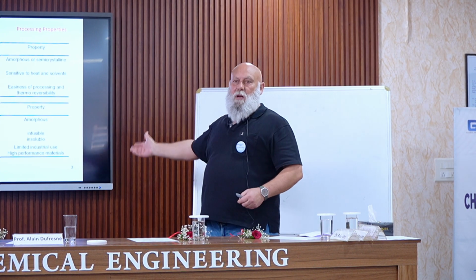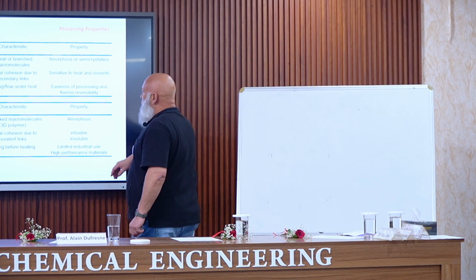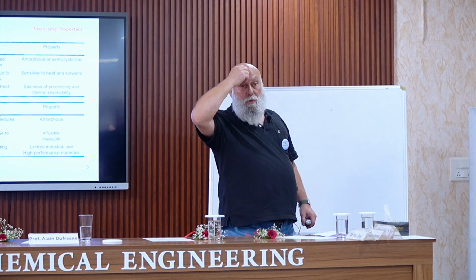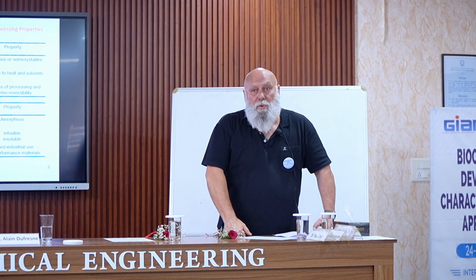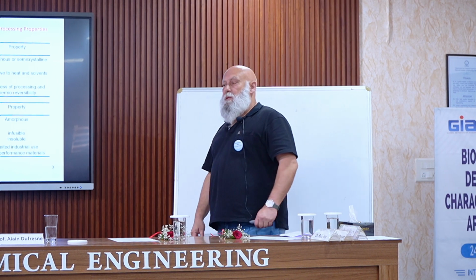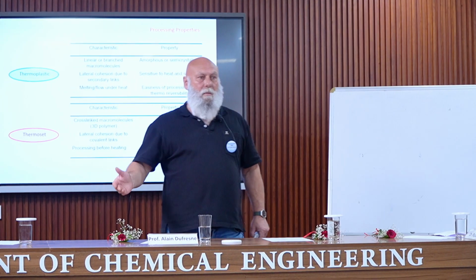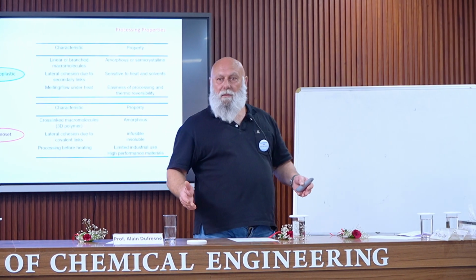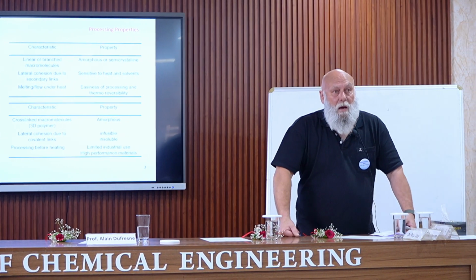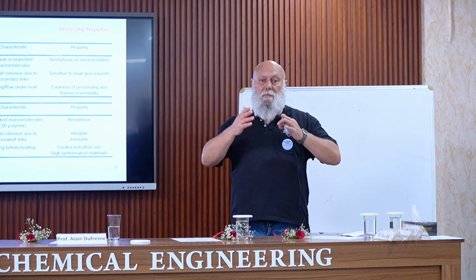Just a comment here, I mentioned melting or flow. In fact, melting is used even for amorphous polymers. Even if you know that melting consists in the transition from a crystal to a liquid. For amorphous polymers, there is no crystal, no crystallinity. But you know also that polymers are viscoelastic materials, meaning that they have a behavior which is between an elastic solid and a viscous liquid.